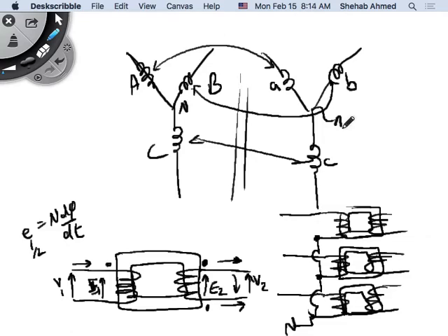And whether I connect this to ground or not is not important in this chapter. It's more important when we talk about protection. So for now, this is how I can construct this transformer. And this voltage and this voltage are in phase as long as the dot here is the same as the dot here. So current is going into the primary here, current going out of the secondary on this top side as well, right? Then the voltages are in phase.